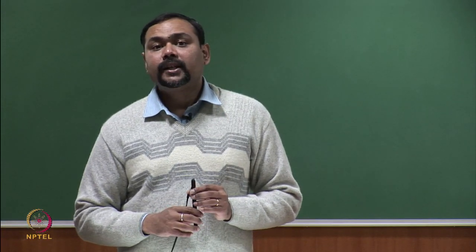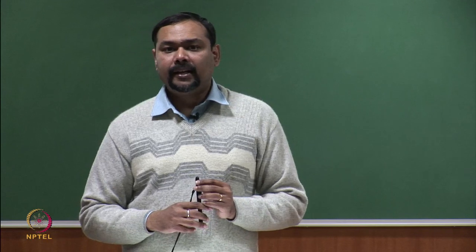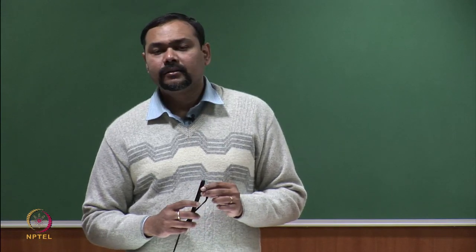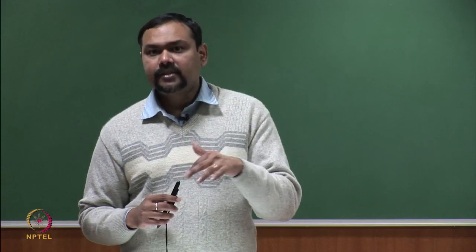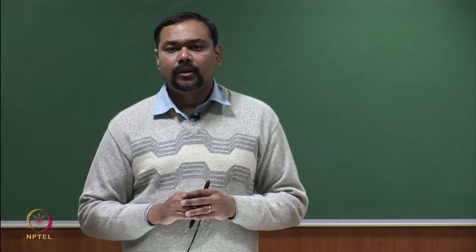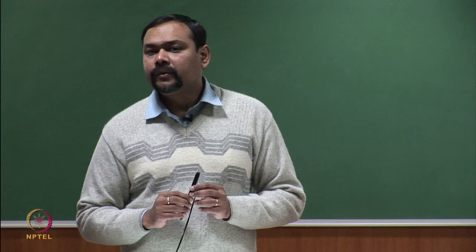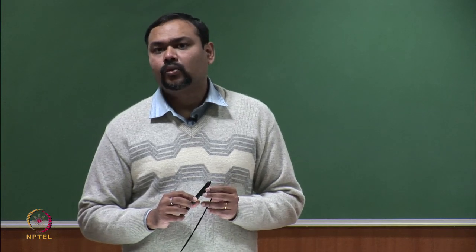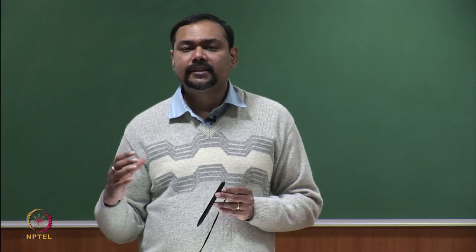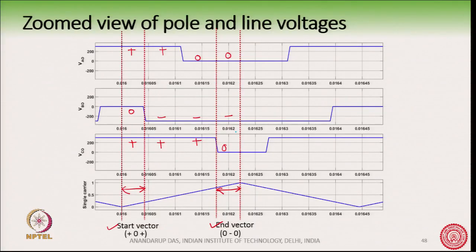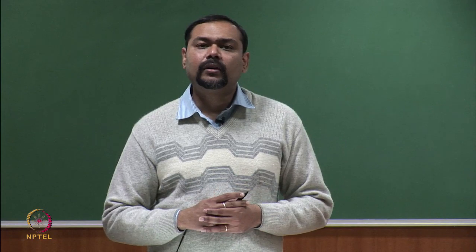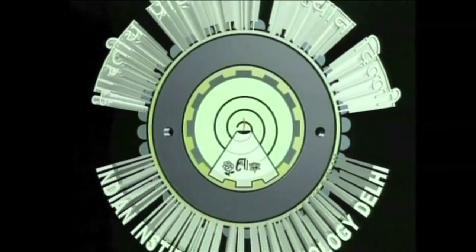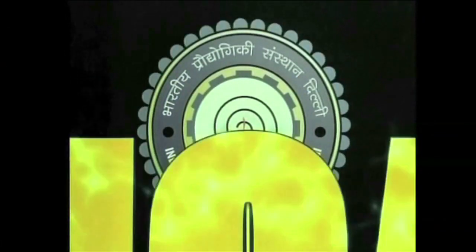Space vector PWM with NPC along with capacitor balancing can also be done, okay, but that requires a little bit of closed loop control, where you sense the capacitor voltages, okay, which we will not cover in this course. So, we will keep it as an advanced study, okay, and so we just cover space vector PWM for NPC.